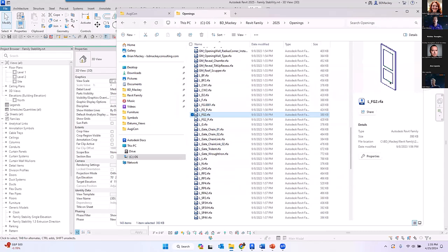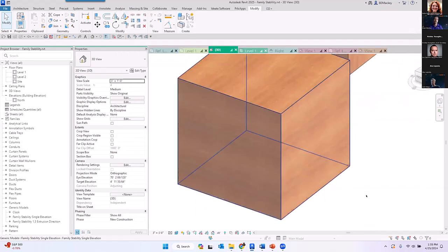I've got a rail as an extrusion. I rotate each one. I don't even do this style and this style as one extrusion. I do each one as an individual, so then I can control those hatch patterns on each one of those independently.